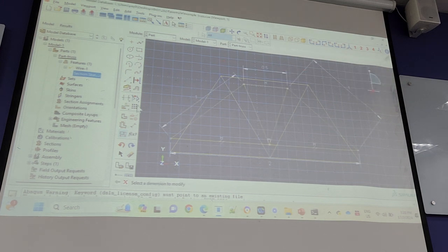Okay? Then, another thing is that just now somebody was asking a very good question. You will see a little black triangle here. Do you see a little black triangle here? That means that you can expand it. Press and hold the button. Then you see your break, your split, your trim, your auto trim.